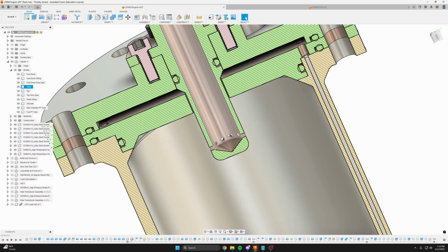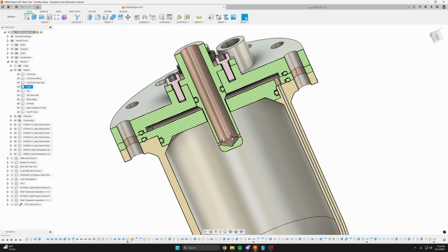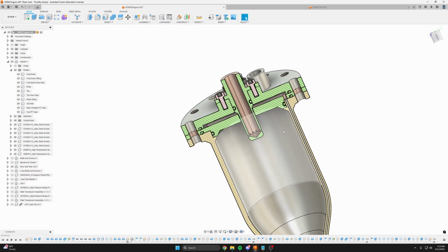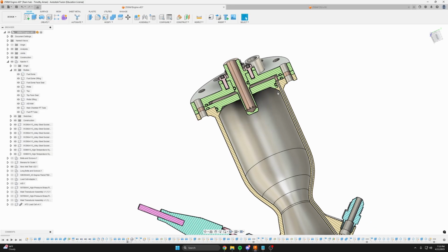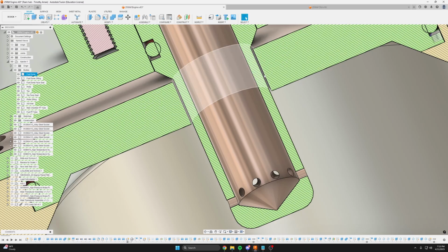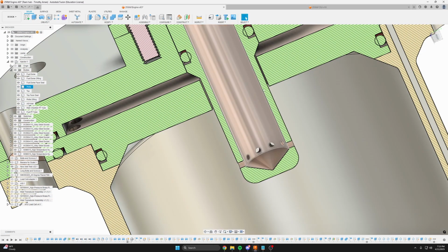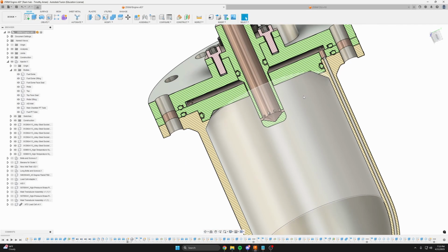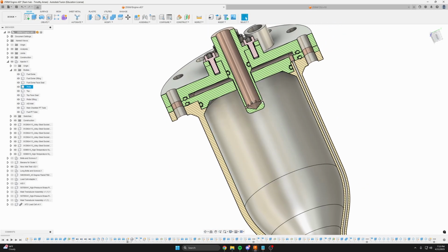So that means there's a higher mass flow rate of oxidizer essentially shooting straight out at the chamber walls, and it will lose some of its circumferential momentum as it gets impinged on by the cylinder or annulus of fuel, but you do run the risk of shooting oxidizer at your chamber walls, so you want some downstream cone angle as a result of the mixing propellants to hopefully not melt your engine.